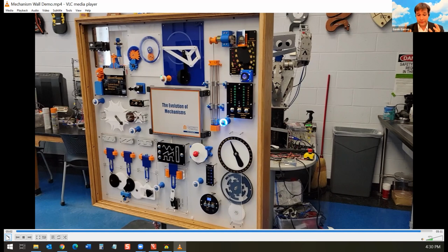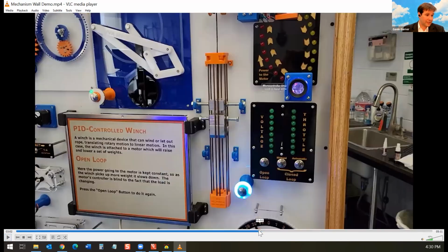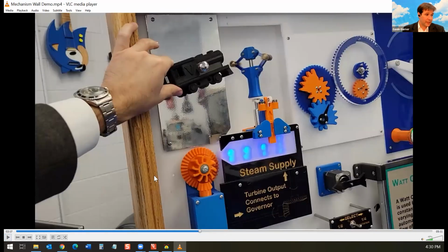and that is again to kind of look into a crystal ball to see what the future holds before you take the time and money to do things. So same with the guitars, it's sort of an exercise where they do the finite element analysis in terms of anticipating resonant frequencies, but it does make the guitars tend to sound better. And then some of the guitars, we made one really fancy one that's shaped like the UVA rotunda, where we really spent a lot of time analyzing it, and we adjusted the shape until we got a perfect resonance at 440 hertz, a concert A.